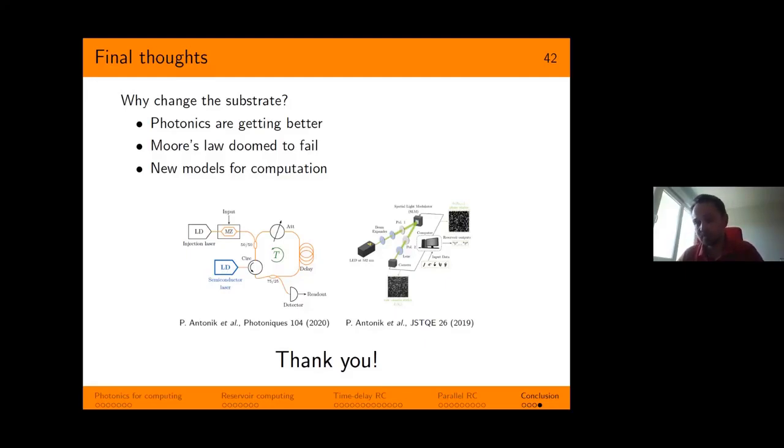So I would see the use of photonic neural networks either in telecommunications, where, for instance, you need to equalize the channel, remove the errors, or where you would need to route the information. So you detect the header, you read the address, and you send the packet to the right optical fiber optically without converting it to digital information to electronics.